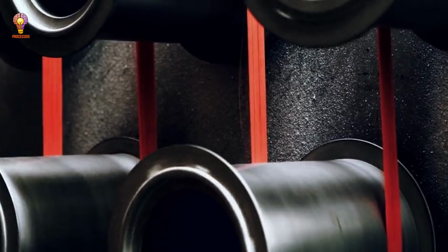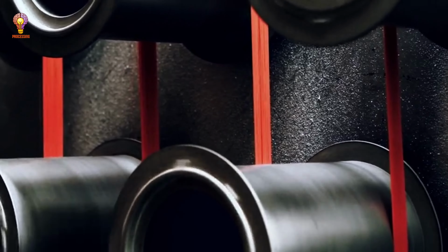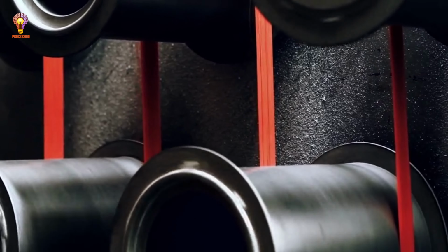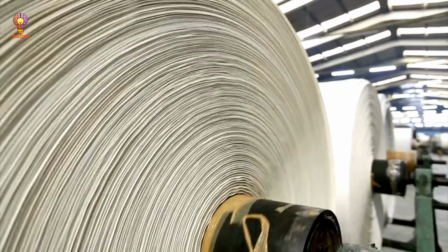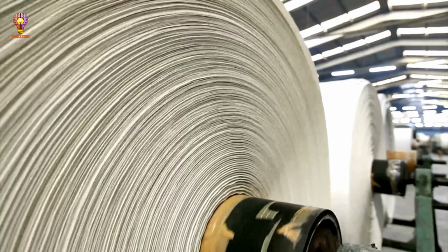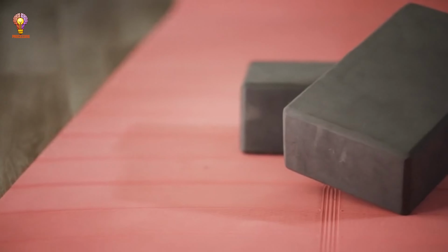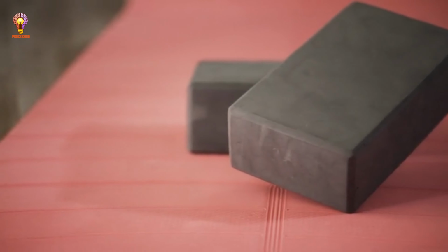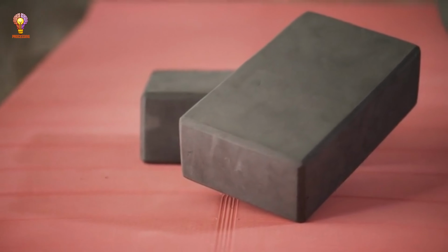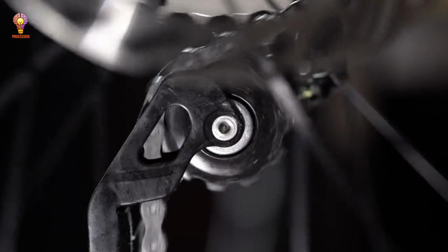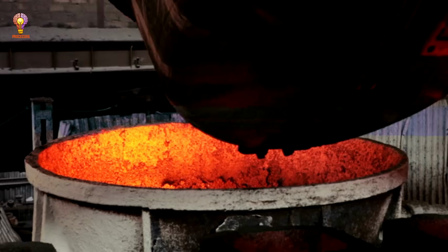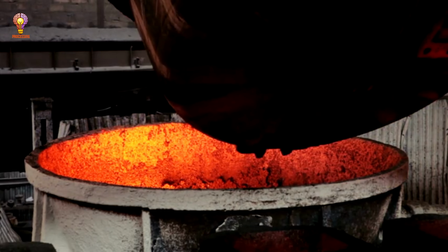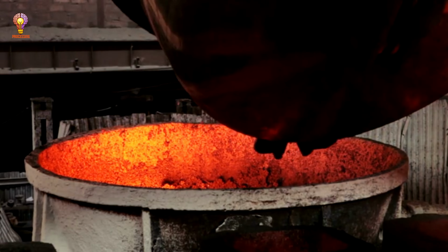2. Advanced alloys and specialized steels. Dual-phase steels, DP steels. Dual-phase steels are used primarily in the automotive industry, offering a combination of high strength and good ductility. These steels consist of two phases, a soft ferrite phase and a hard martensite phase. The combination allows these steels to absorb energy in a crash while still being lightweight. The steel's properties can be tailored by controlling the heat treatment process.